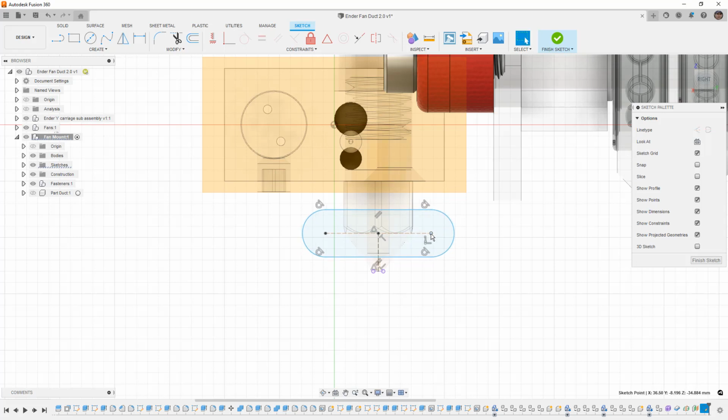Now, again, depending on the specs of the fan, how much back pressure it can take, how much flow we want, you would need to play around with these different opening sizes. Because I'm going to assume that nobody is building this duct system for this specific machine, other than the person that sent me this, I'm not really too worried about dimensions here, but we are going to add some dimensions just to go through the process.